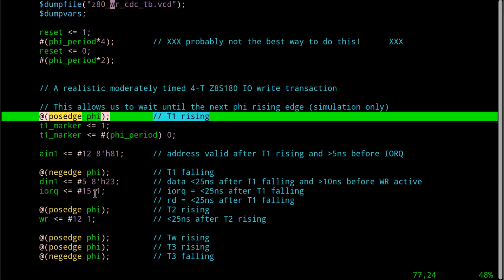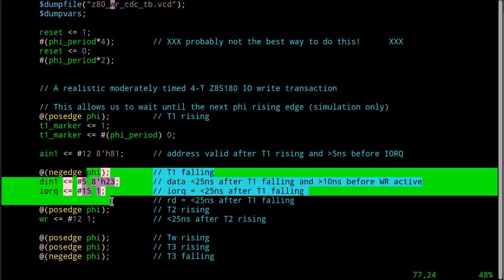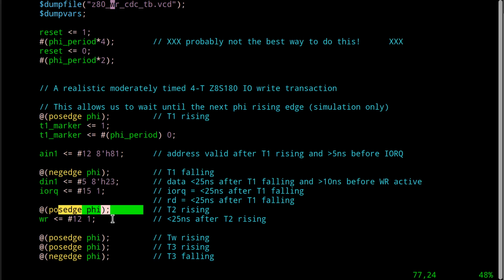Then proceed. Okay, great. It's the same definition in the always block when you use them in your real modules, in your synthesizable modules. Wait until that happens, and when it does, execute the body of the module. It's a while loop. It's forever, do this, and wait for this to take place, then do all the stuff down here. And then what we're going to do is say, wait for that to take place. It could be something else. Do this, wait, do, and so on.